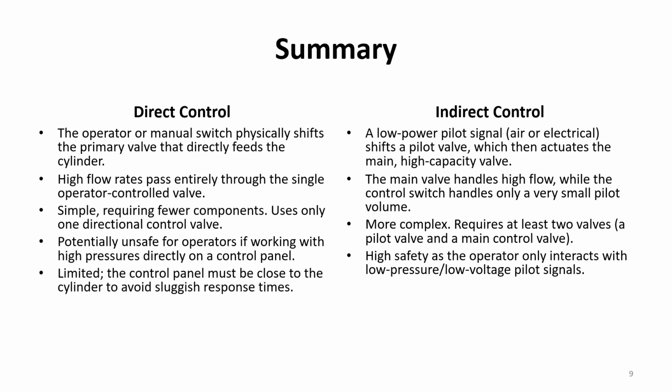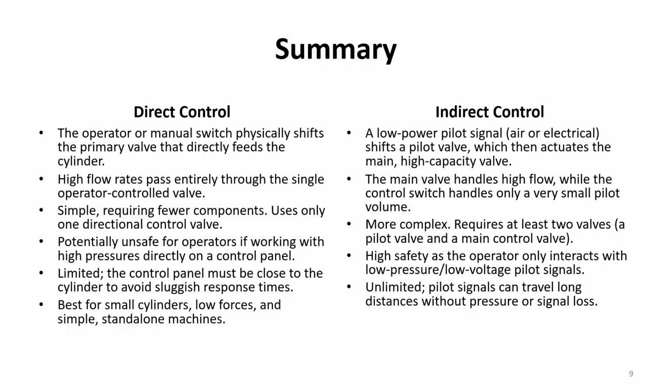Distance wise, the installation requirement for direct control valves is limited, and the control panel must be very close to the cylinder to avoid delay in the response of the valves. Whereas indirect control circuits are typically designed to be used over longer distances, and hence they can be set up over unlimited distances, and the pilot signal can travel long distances without pressure or signal loss.